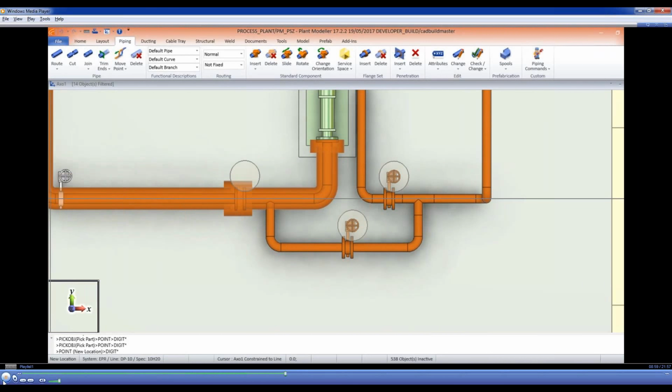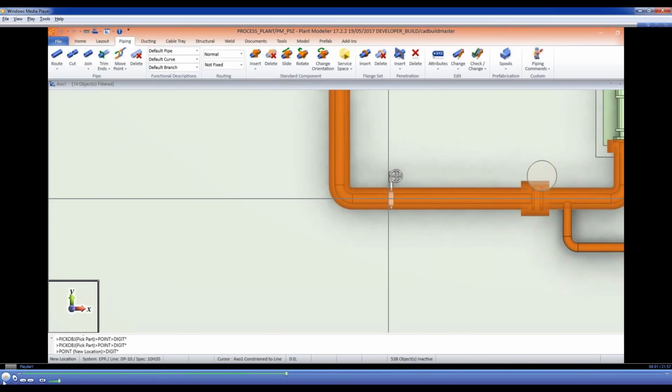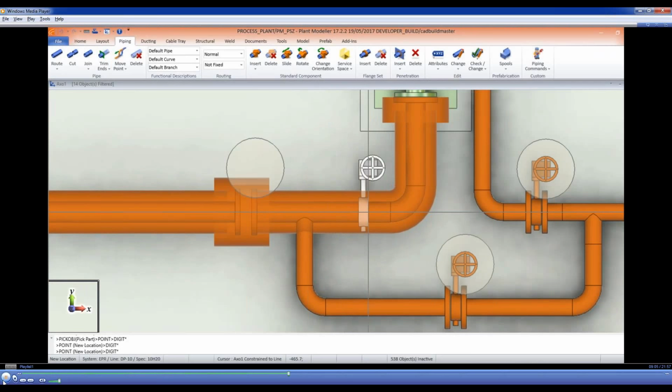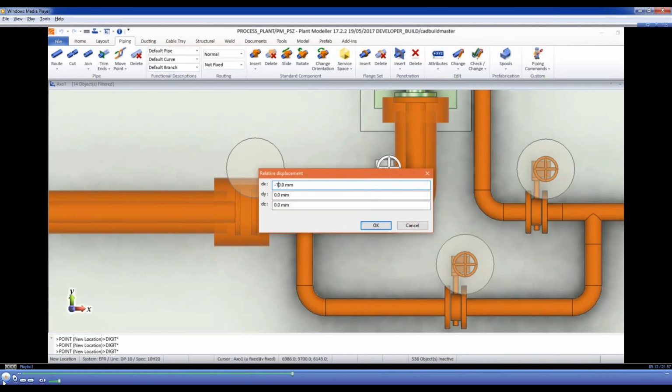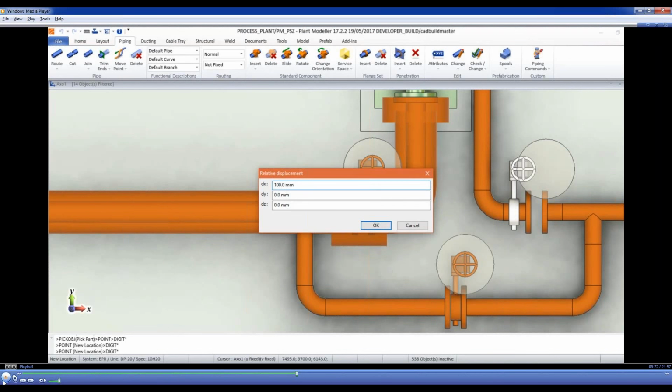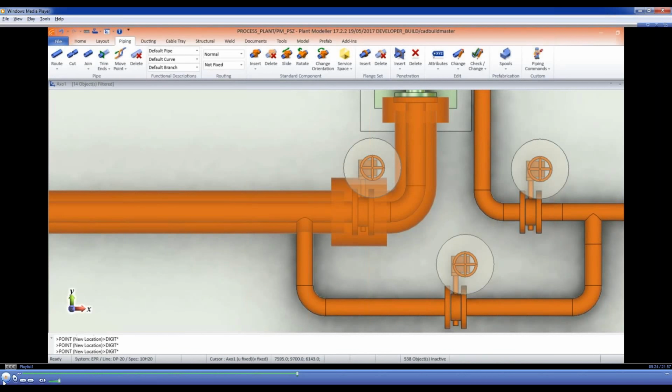It's simple to fix just by sliding the valve to the correct place. I will pick it. I can move the valve inside this one pipe. I can use left justify, right justify, or center justify. And then I will measure a reference point 100 mm from the seam of this elbow. Same thing at the other side, and same distances. And the third one.